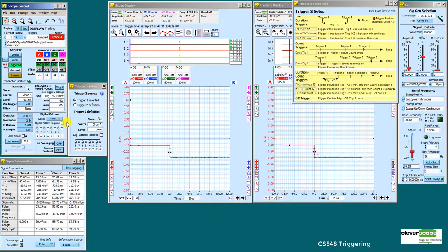So it triggers because it never sees the rising edge, the opposite rising edge, the one we want here in that trigger time, or if it's less than this, it triggers until we get down to 60. Now it doesn't trigger. Now it triggers. It's not triggering. So we can detect, for example, a pulse that never completes, or look for something that hasn't happened properly.